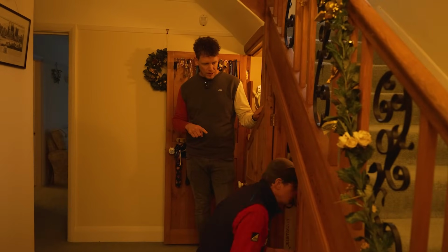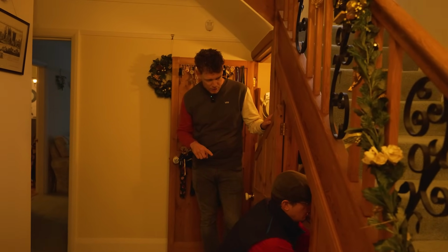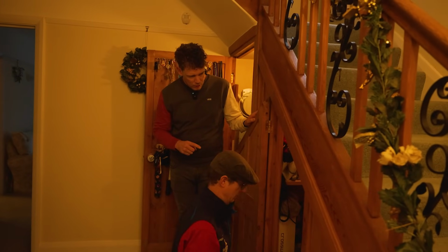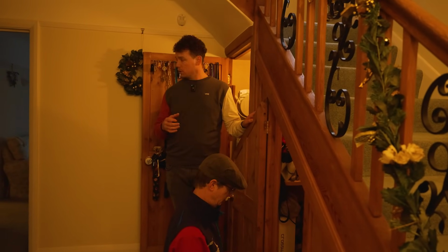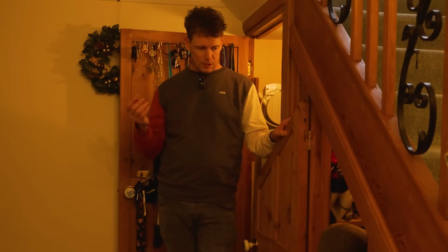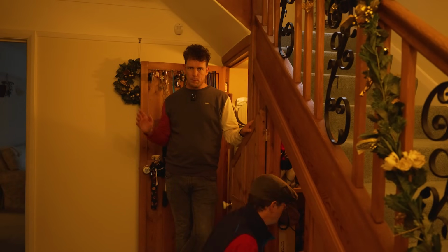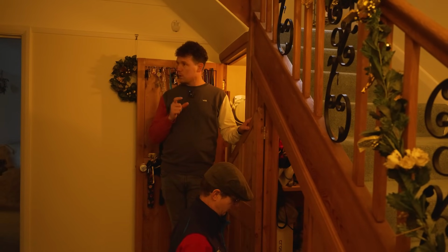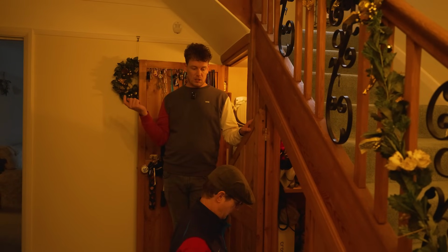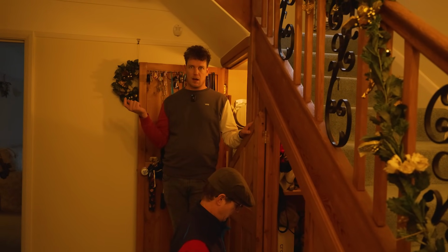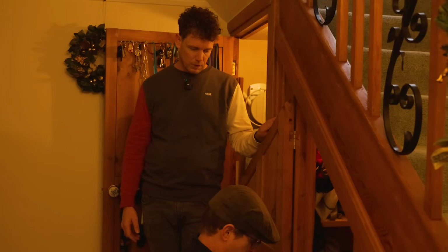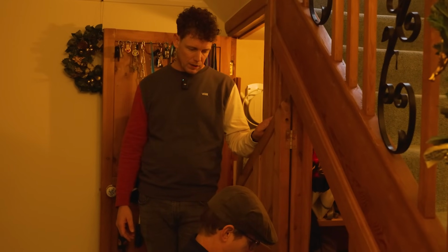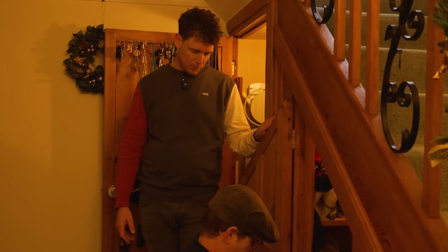Right. Okay. Tom is taking information such as the incoming fuse, main cutout fuse size, and a spare way in the consumer board, which basically means a spare power outlet for the heat pump. However, we've already got one installed, so we'll just be using the current one. Really, for this job, we're checking that the current installation needs upgrading at all. It was installed properly. If we just sort of trusted what they put in, we might end up in a bad situation.